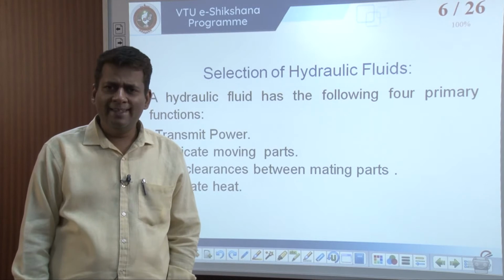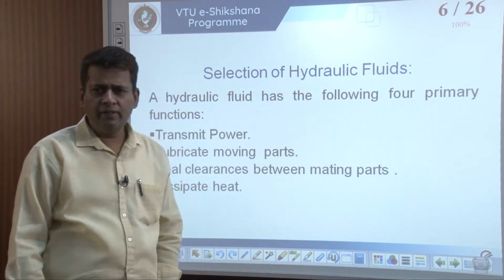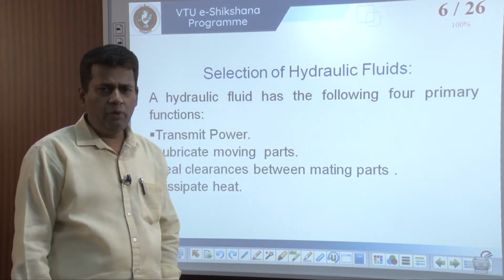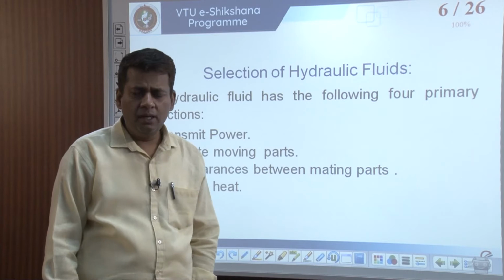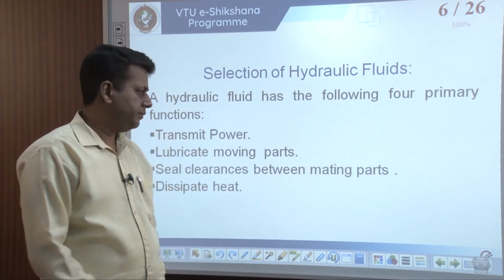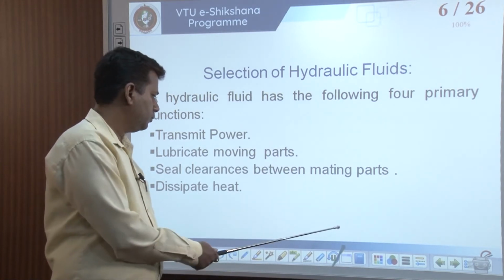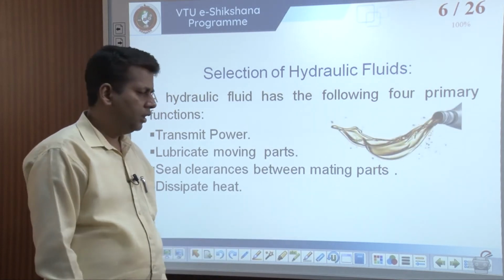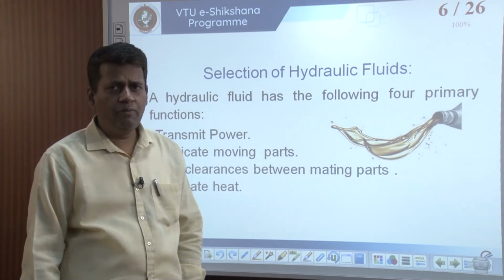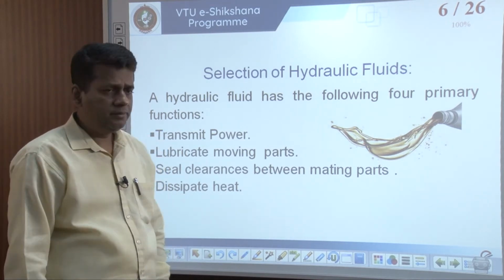Also, it should dissipate heat because heat is generated when two surfaces are rubbing, and this hydraulic fluid will physically separate these two surfaces and the heat is dissipated. So, these are the basic functions of any hydraulic fluid. So, they are used for multifunctional purposes.